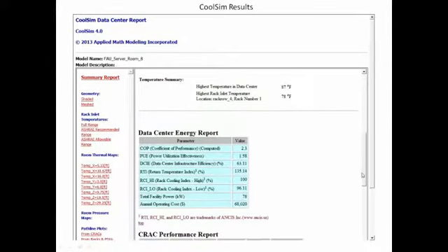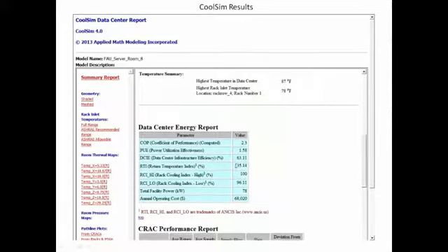So as we scroll down and take a look, the first thing I notice is that the return temperature index is 135. That should be 100%. This means that my racks are going to try to recirculate upon themselves because the flow rate coming from the cooling units isn't sufficient to meet their needs. Now, fortunately, I don't have any hot spots. My RCI high is at 100%, but my RCI low is at 96%, which means I've got some cold spots on those rack inlets as well.